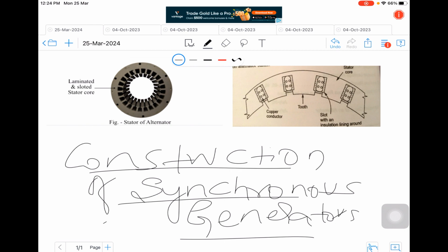When we rotate the field, a large AC EMF is developed in the armature. As it is stationary, large space can be provided to accommodate a large number of conductors and the insulation. Also, the armature gets protected from mechanical and electrical stress.